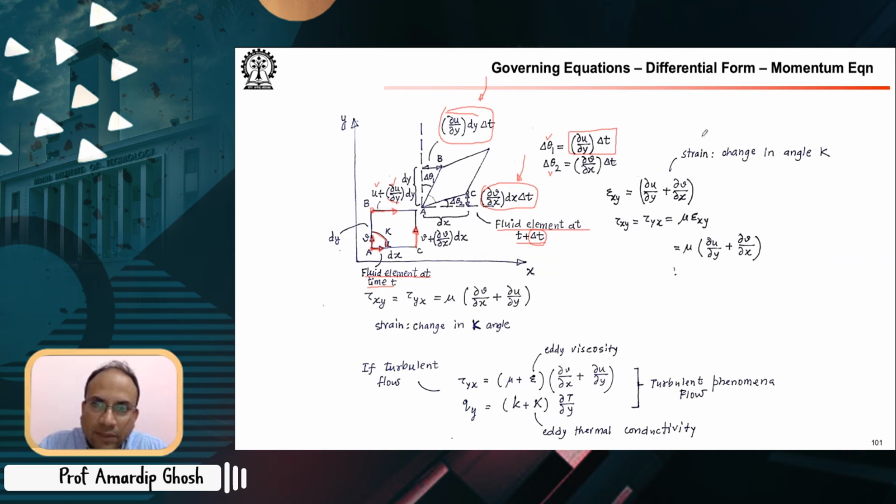the rate of, so this is the strain rate. So strain rate is given by delta theta 1 by delta t plus delta theta 2 divided by delta t. So this gives you the rate at which this angle is shrinking or changing. So that is the strain rate. In some cases you also have a dot on top of it, but you can just stay with this convention.